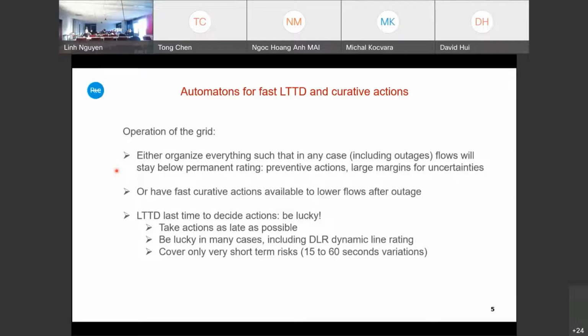Today, in some areas in France, near Poitiers or Niort, day ahead, people see that tomorrow the lines will be at 70%. Fine. And in real time, that day, they see 100%, and they have to switch off a lot of wind farms. This is not bad work of weather forecast, nor bad work of wind farm generation forecast.